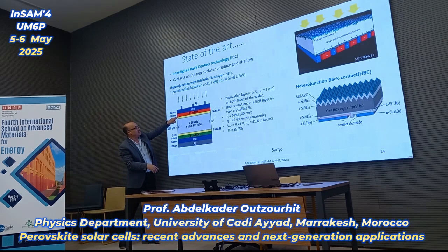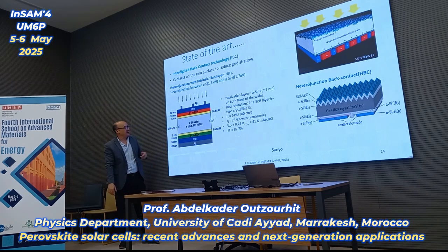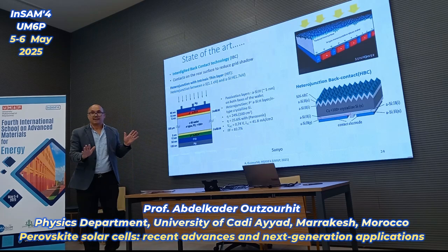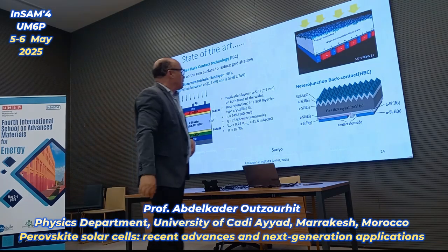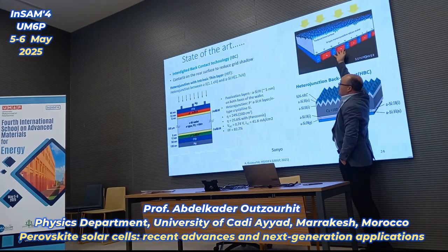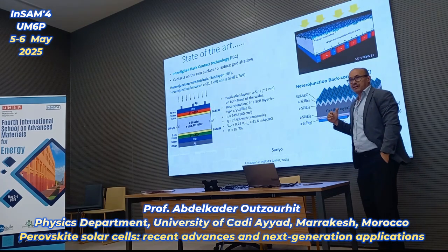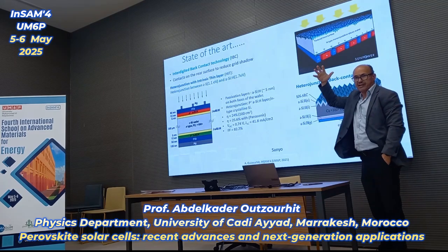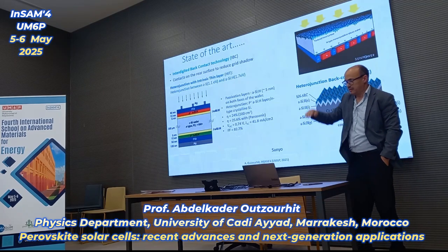And then you make your heterojunction here between the P+ amorphous silicon and the N-type silicon. But you see, it's the same structure. You have an absorber, N+, P+. It's the basic structure they showed you in the beginning. The same thing for the front contacts. These contacts are just managed at the back of the cell. No contacts are made at the front, so that you reduce the shading effects due to the current collectors.